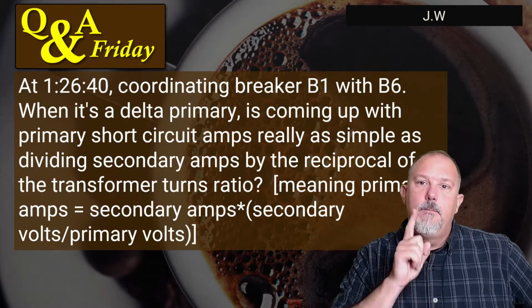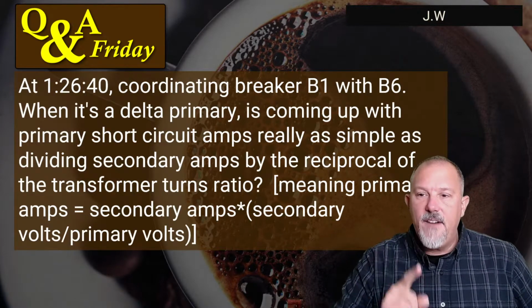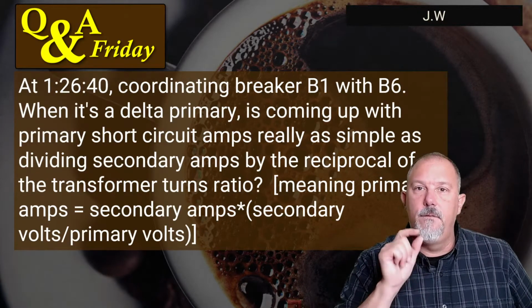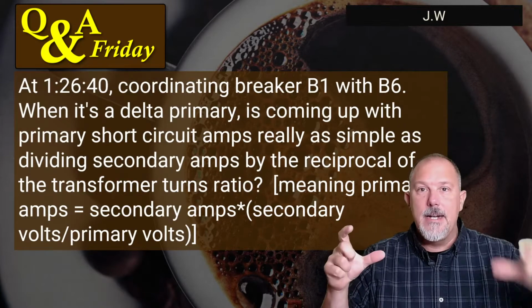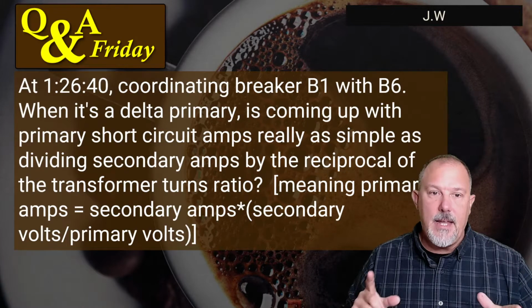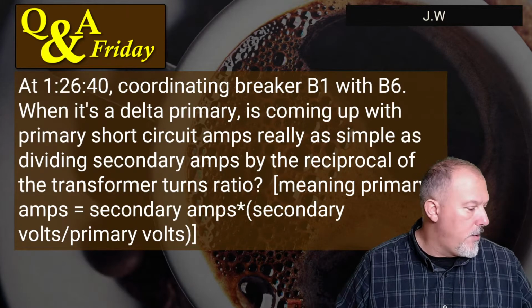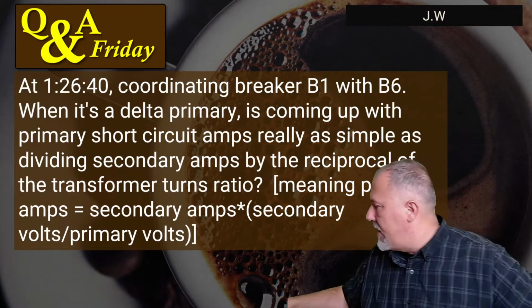but here's the important part. You have to pick the right voltages. Line to line, line to line. Don't make the mistake of taking a line to neutral voltage. Now remember, delta Y ground, what's he talking about?